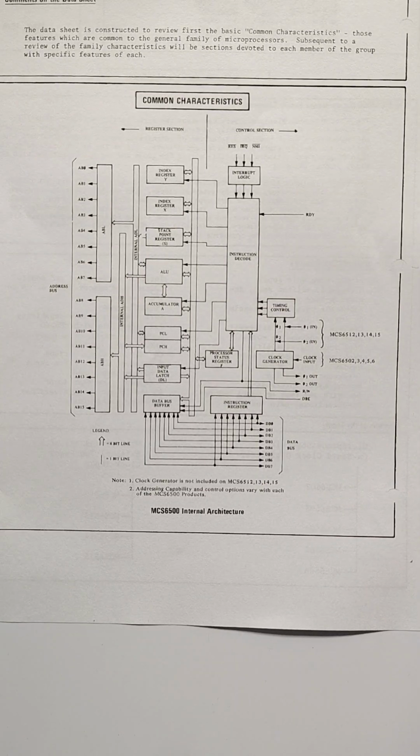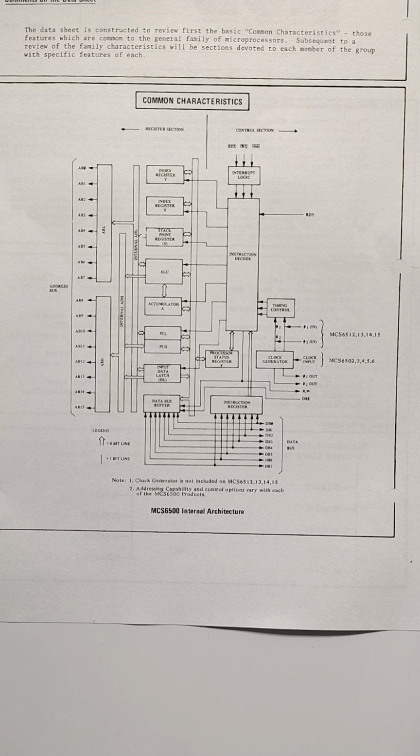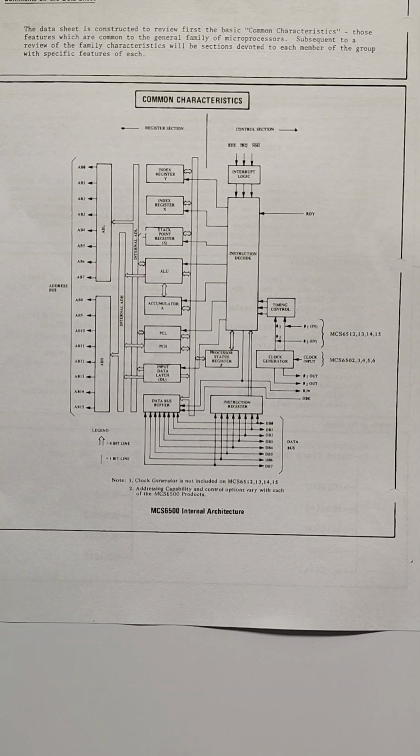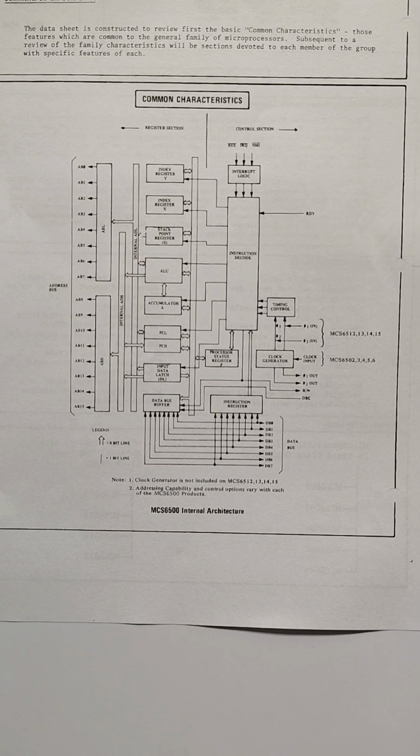Another thing is, previously in the microprocessor world, they were using NMOS enhancement mode. And this required multiple power supplies, and it complicated the design substantially. The 6502, however, was built with depletion mode transistors. This eliminated the need for multiple power supplies.